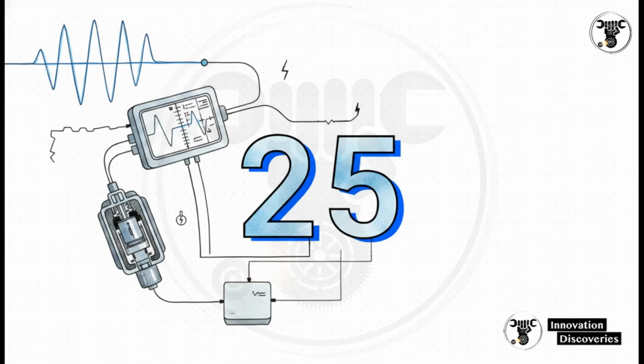To figure that out, we pivot to analyzing the live electrical signal coming from the engine computer. By hooking up an oscilloscope to the solenoid control wire, you can definitively verify if the ECM is actually transmitting that PWM signal. You are looking for a nice, clean, square wave pattern, typically running at a frequency anywhere between 25 and 100 Hz. If you just have a flat line on the scope during the correct operating conditions, well, you've just ruled out the solenoid. You are now officially hunting a wiring fault or a blown ECM driver circuit.